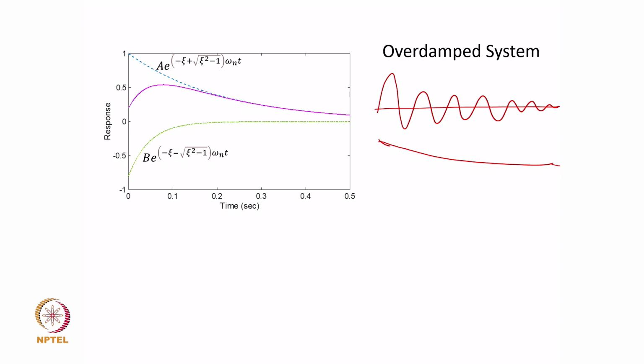If you want the system to come back quickly without oscillating, the damping should ideally be targeted to be zeta equal to 1, because with zeta equal to 1 there are no oscillations, and if the requirement is that there should be no oscillation, then the earliest you can arrive at the mean equilibrium position without oscillation is with the damping factor equal to 1.